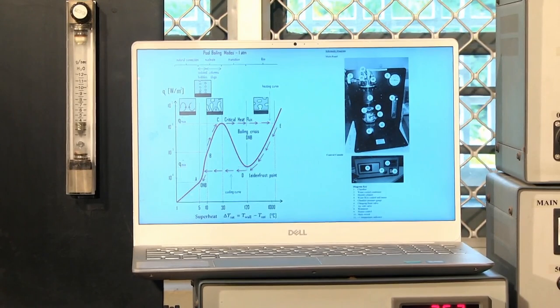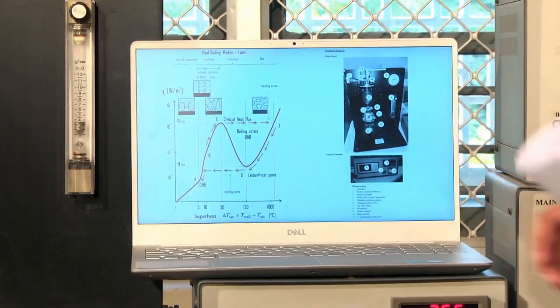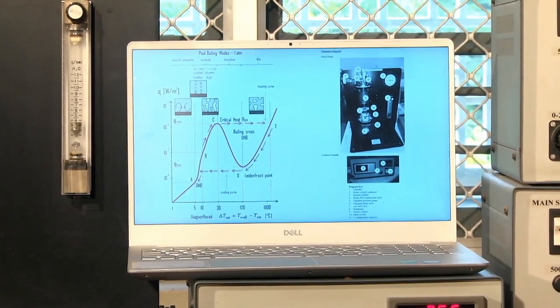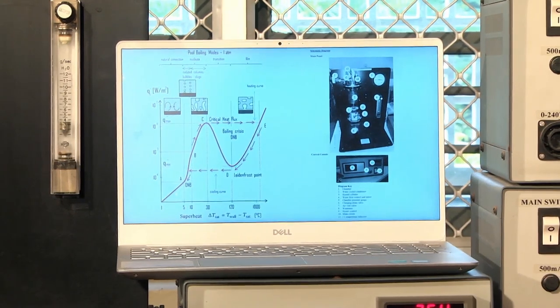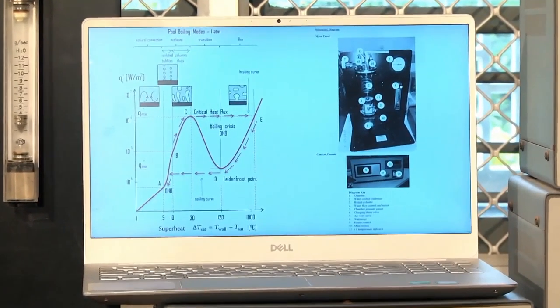As we increase the heat flux, we can see the formation of small bubbles, which is the regime A to B here. We see small bubbles forming, but these bubbles collapse when they reach above the boiling surface. When we further increase the heat flux, we will see some column kind of bubbles which are vapor slugs. These bubbles reach up, and they release the heat through evaporation, and they release an enormous amount of heat because of their capability to transfer latent heat.